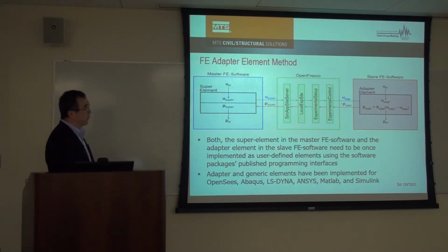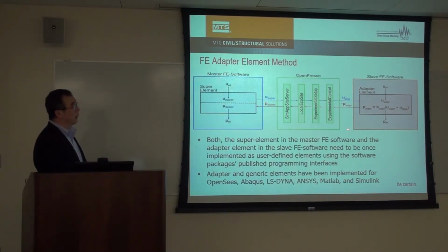In this case, we can simulate the hybrid test, and we have done that quite a few times. Because the interface is OpenFresco, it can be coupled with all kinds of FEA packages. So this part could be OpenSees, could be ANSYS, Abaqus, and this part could be some other things.